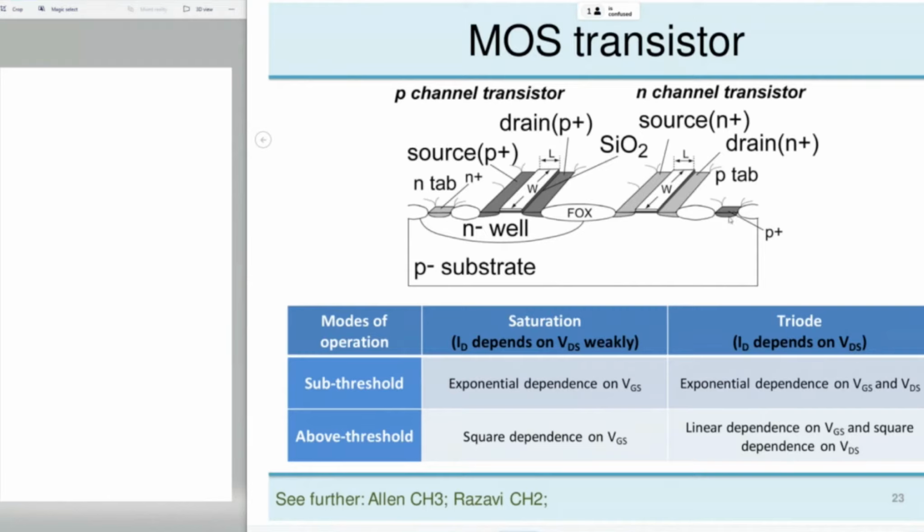And you see that it needs to be always the lowest potential in our circuit, so that this parasitic capacitance, this parasitic diode that we have here between the drain or the source area, which is N plus area, and the P substrate is reverse biased. So this parasitic diode should be always reverse biased and not turned on. Otherwise, there will be big currents and will melt our device.